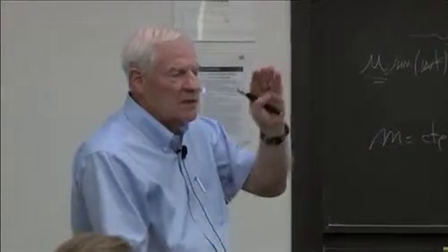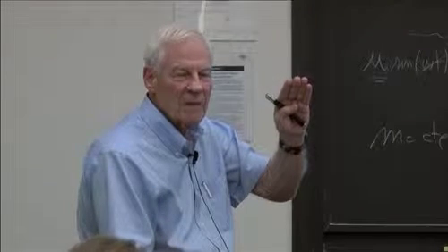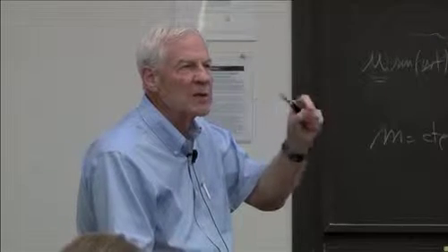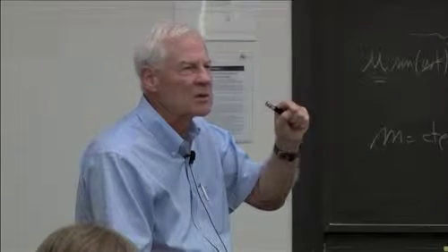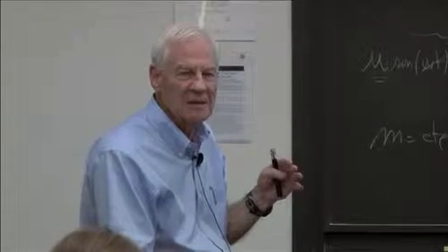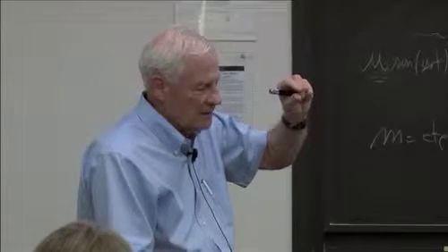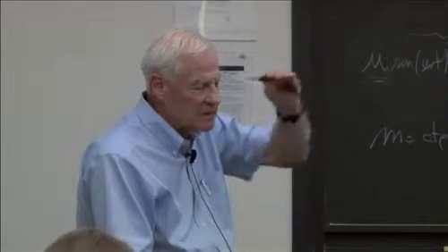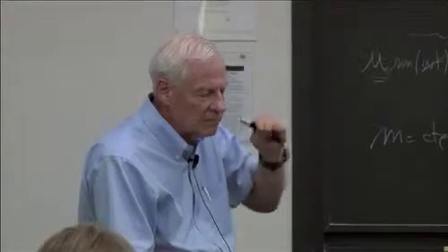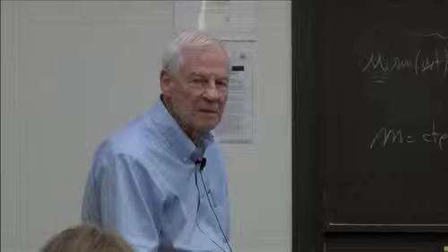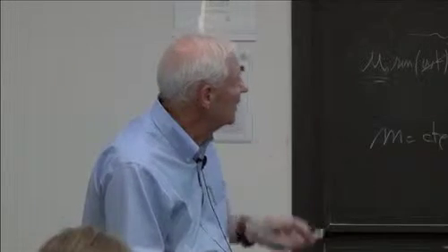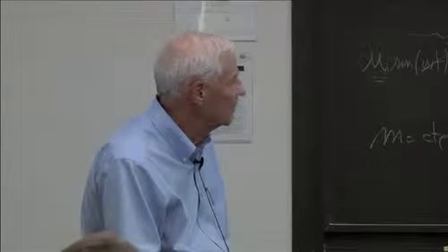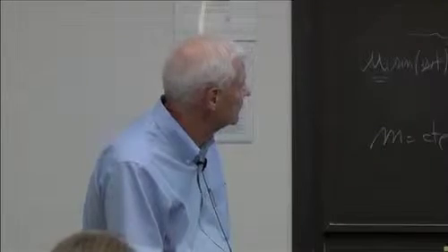Ignition delay time might have an activation energy of, say, 40 kilocalories. That means that at, say, 2,000 degrees, 1% error in change in temperature is maybe 20% change in ignition delay time. It kind of goes, delta k over k, the rate coefficient, goes like Ea over RT, delta T over T. So that Ea over RT, that multiplier of, say, 20, is a big number. So you have to really pay attention to temperature. Even a 1% change in temperature is important, and we can't neglect it anymore. People used to neglect it.